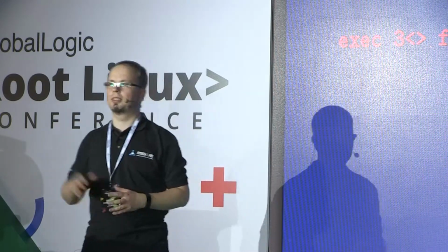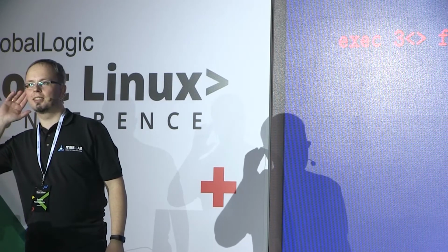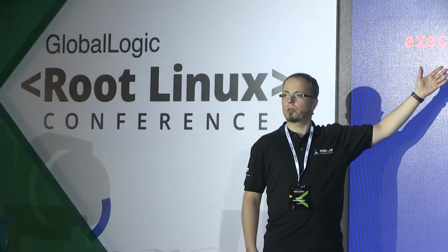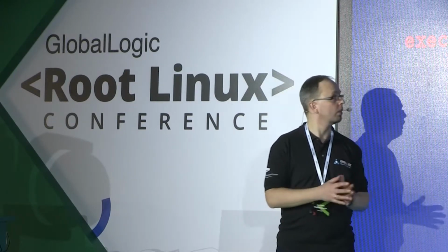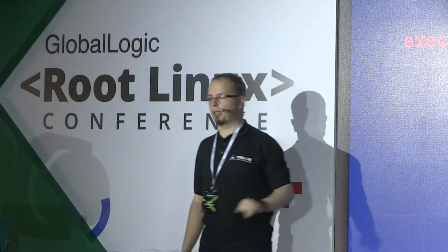Can't hear anyone. No. So it can be considered a kind of redirection. It's the way we use file descriptors in bash. The question is, why use file descriptors at all? Well, the answer is because of the way function.fs is implemented. Whenever you close EP0, it means you are done with your function. It ceases to exist, and your gadget gets unbound from the UDC. This way, we open it, and we keep it open for the lifetime of our gadget.